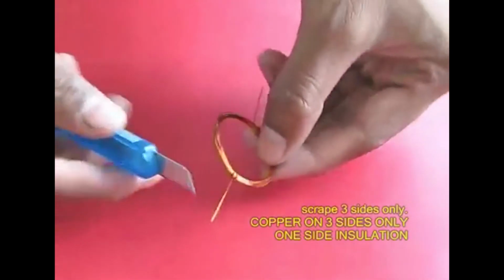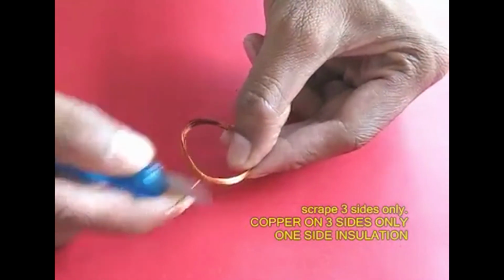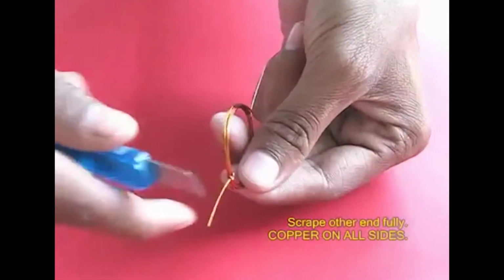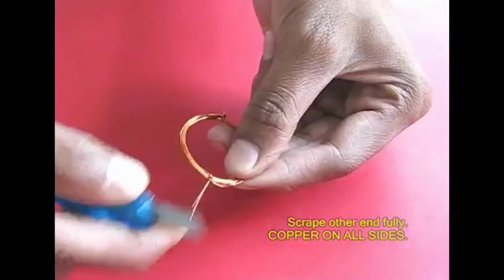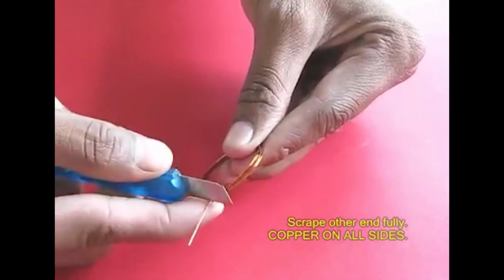Now take a knife and scrape off the insulation on 3 sides from one end. One side would still remain insulated. On the other end, scrape the insulation on all 4 sides, and there will be all copper on this side.